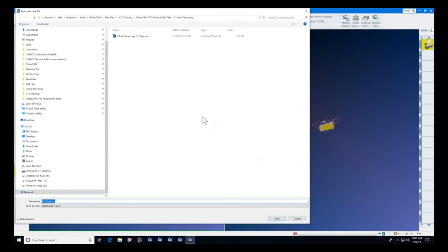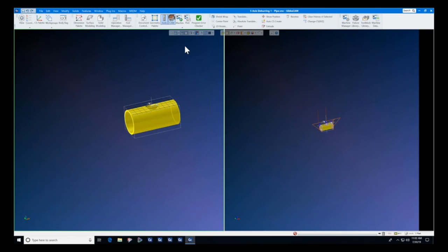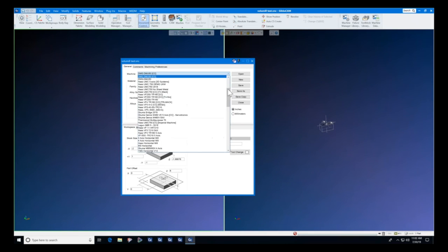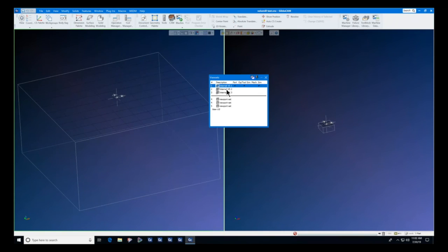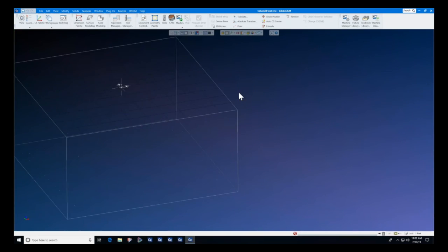We're going to make another new file. We're going to call this volume mill test. We'll make a quick part here on a 3-axis mill part, 3-axis vertical mill. And let's see if we can force that error so we can fix it. We're going to make this 2 minus 2, 0 minus 2. And let's make a pocket on this part. We'll use a single viewport. A simple pocket is all we need.